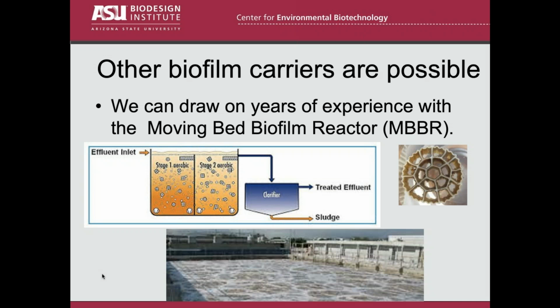Now, you don't have to use granular activated carbon. You can use other media, and we can rely on the developments of biofilm media for the moving bed biofilm reactors, the MBBRs. Here I'm showing a schematic of an MBBR, and then to the right, an example of one of these MBBR carriers.